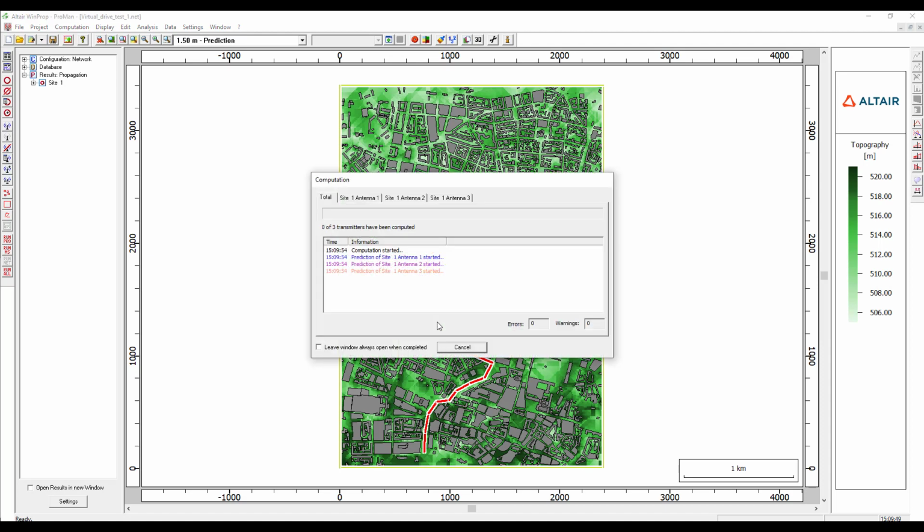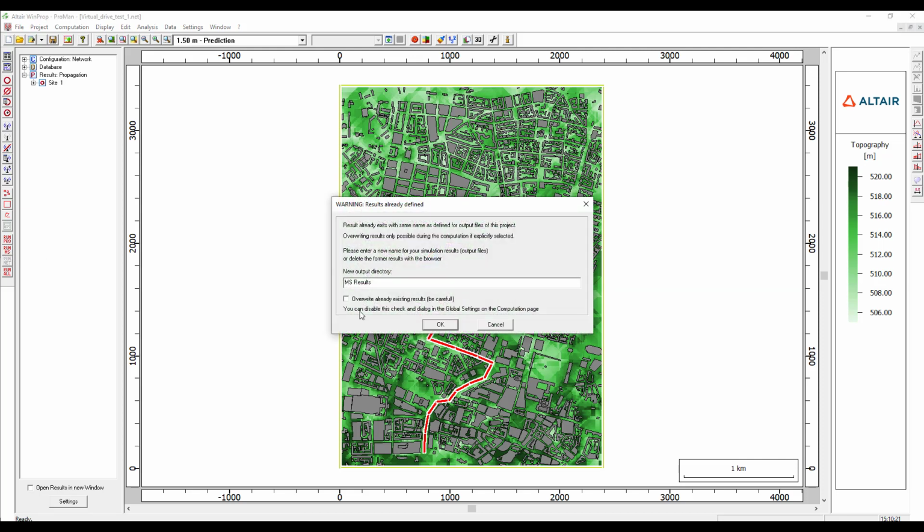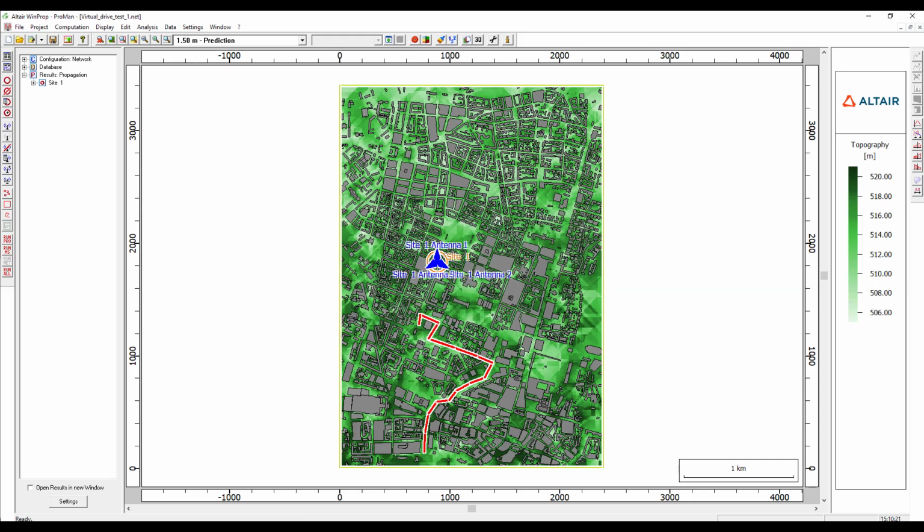It will now be done on a smaller area, enough to cover the trajectory. Use Run Mobile Station or Run MS to simulate the mobile station, now moving along the trajectory. Receiver antenna pattern makes turns along the trajectory as if mounted on a vehicle that drives the trajectory.